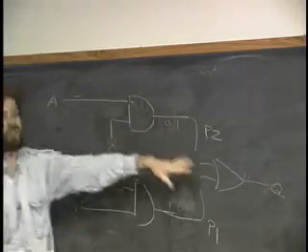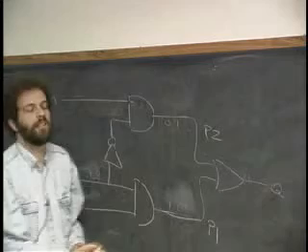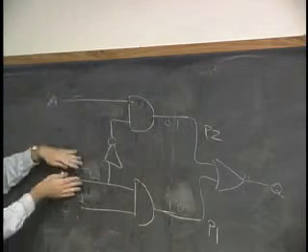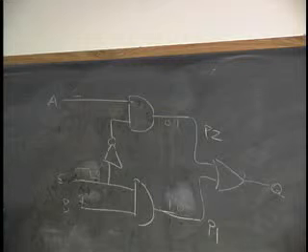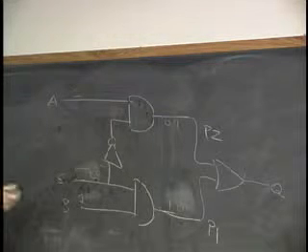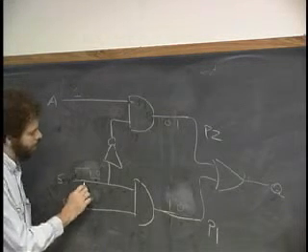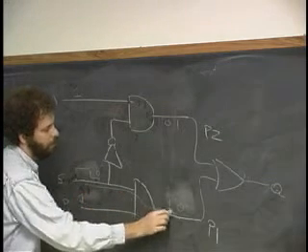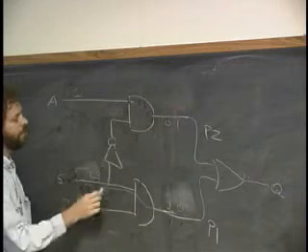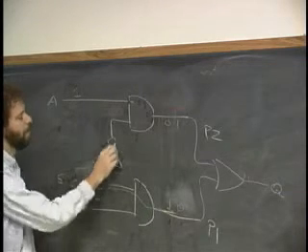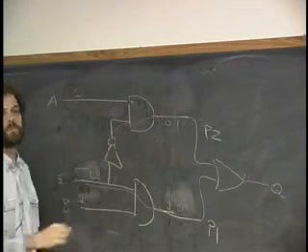And then an OR gate which combines them all in the big race. Okay? So there's a bunch of mice here, right? And then there's these little gates that let the mice go through. Okay, what's the trouble? The trouble is that this path over here to shut off P1 involves less logic than this path over here to turn on P2.